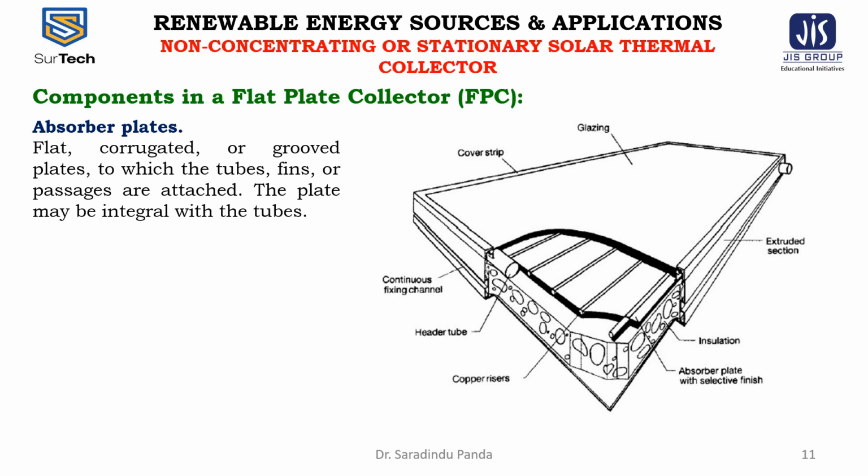Selective surfaces are particularly important when the collector surface temperature is much higher than the ambient air temperature. An energy efficient solar collector should absorb the incident solar radiation, convert it to thermal energy and deliver the thermal energy to a heat transfer medium with minimum losses at each step.